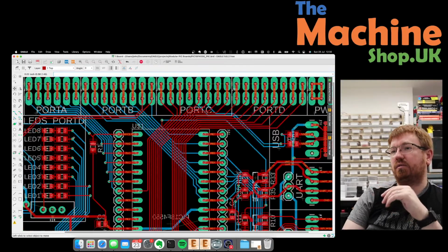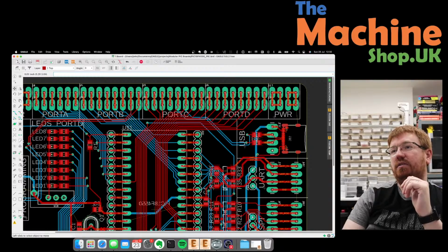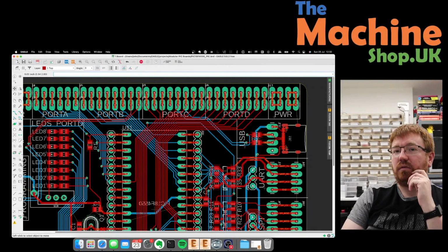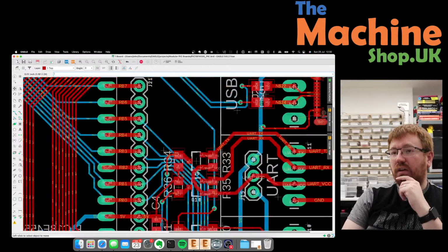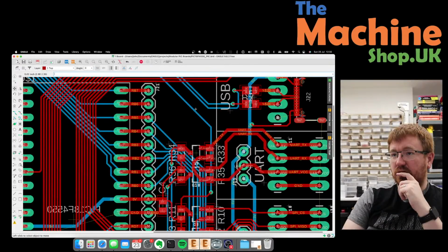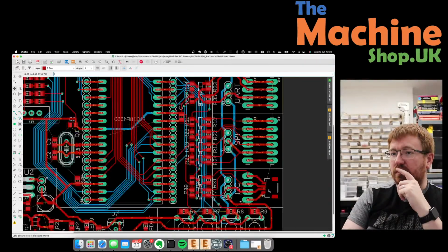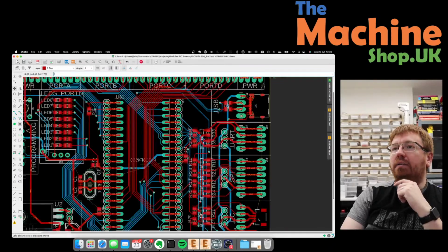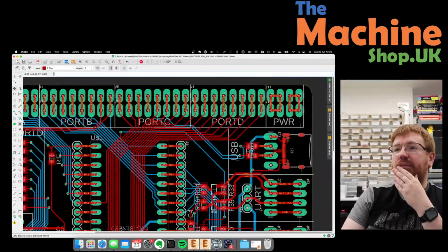It's not going to cause a problem with the LED unless somebody decides to use port D for something else, but I don't think it's much of a problem. And I don't think any of the communications buses, the RCs, use the D port, so that's okay.